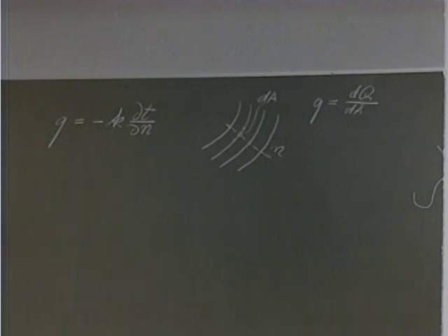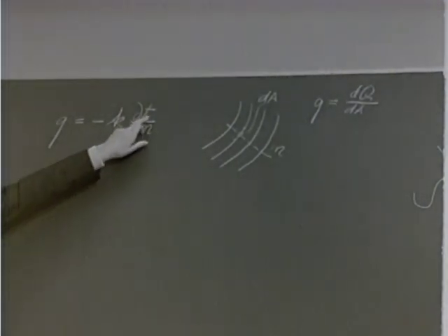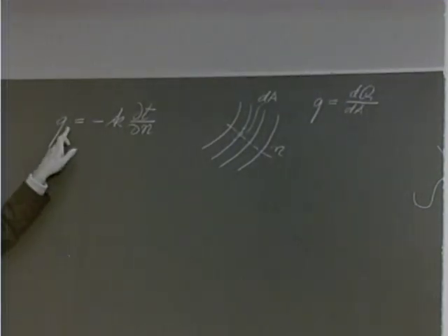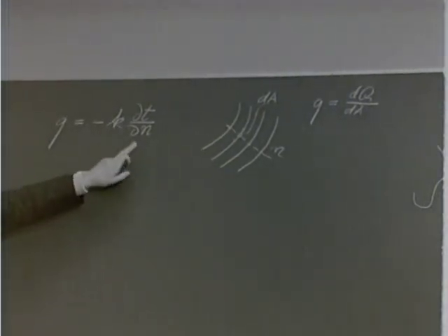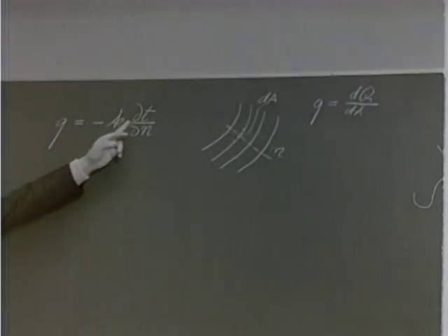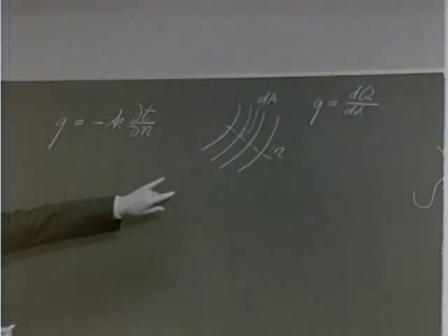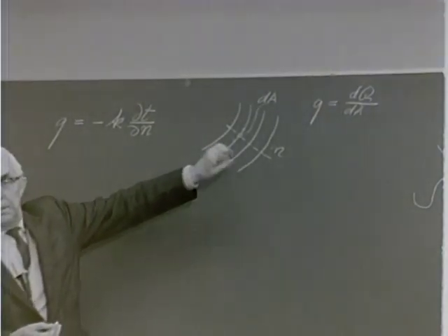For this purpose, since we really have in our equation two unknowns, we don't know the temperature and we don't know the heat flux, we have to get some other considerations. We assume that the conductivity, which is a property of the material, is known. So q and T are the dependent unknowns. We have to make some other consideration, and we get this, as I mentioned the last time, from a heat balance.